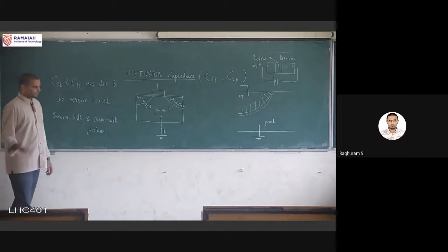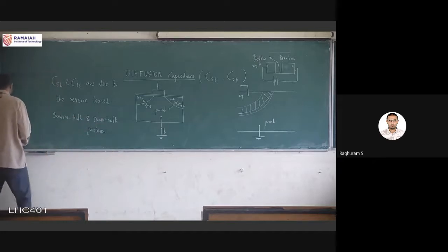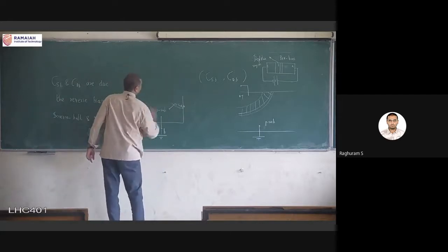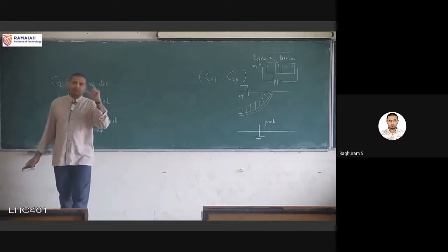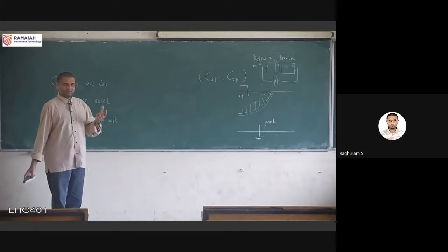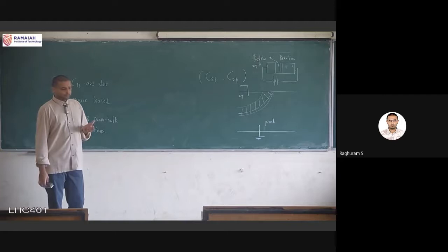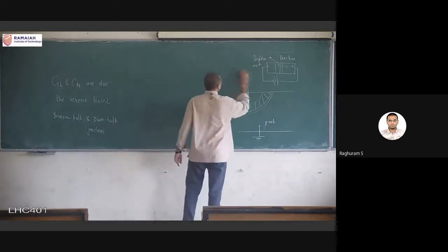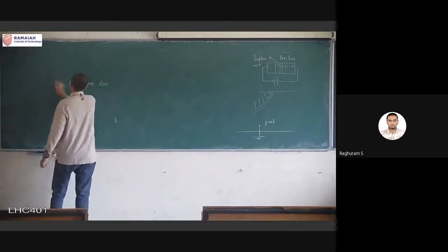So together we have talked about the overall picture. So let us put it all together and draw this very important diagram. That is the diagram of all the capacitances associated with a single transistor. That is, I have one transistor. It might be NMOS, it might be PMOS, and in NMOS and PMOS, the nature of the capacitances are all identical. There is no difference at all. Only the values depend on the size of the transistor, but the sources and the nature of the capacitances are identical.